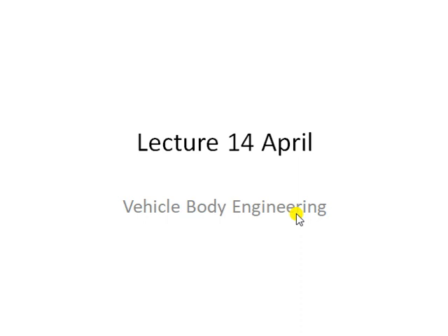When you suddenly apply a brake, the weight on the vehicle body shifts from the rear axle to the front axle. So there will be a change in the load distribution of the vehicle, and whenever there is a change in the load distribution, its center of gravity may also travel, and due to this a whole lot of dynamic situation arises on the vehicle.